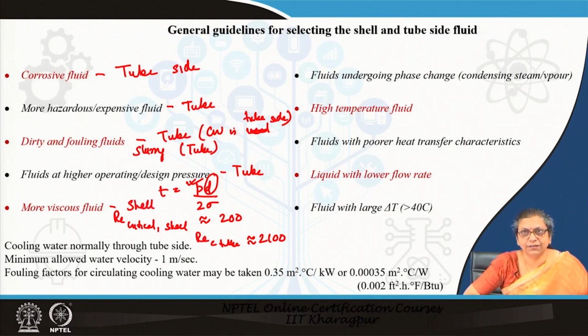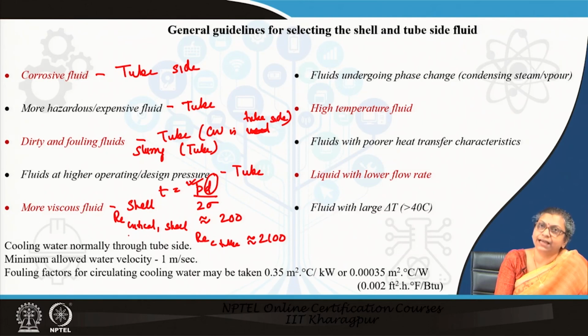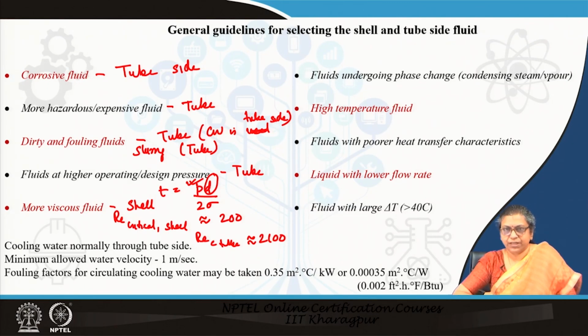But remember one thing, if the fluid is so viscous or the velocity is so low that even in the shell side it exhibits laminar flow characteristics, under that condition, in order to increase the velocity, we would like to introduce the fluid on the tube side.